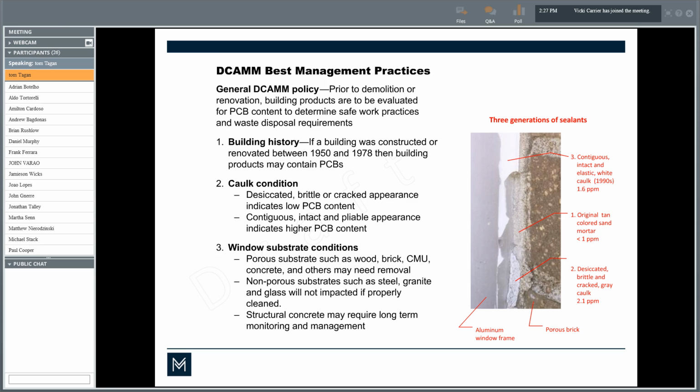So a building that was being supported by a 12-inch by 12-inch column suddenly was going to be supported by an 8-inch by 8-inch column, in which some of the reinforcing steel was now going to be exposed. And so we were asking the consultant if they were willing to stand underneath the building while we took these inches of concrete off. And they quickly understood that you really can't do that. So you have to look at other measures on how to deal with PCBs and structural concrete.